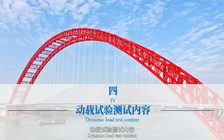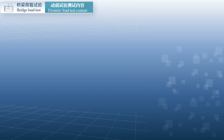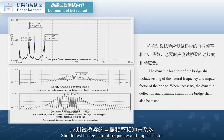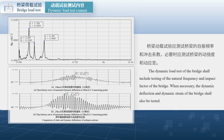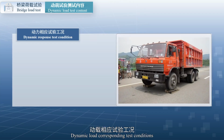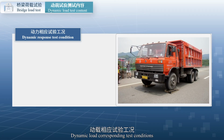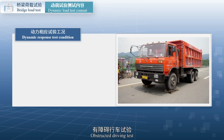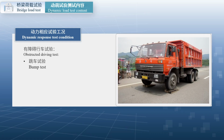4. Dynamic load test content. Bridge dynamic load test should test bridge natural frequency and impact factor. When necessary, the bridge's dynamic deflection and dynamic strain should be tested. Dynamic load corresponding test conditions include unobstructed driving test, obstructed driving test, and braking tests.